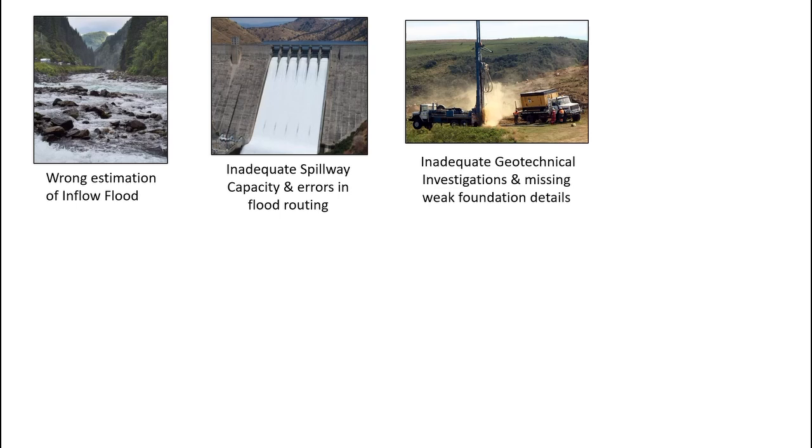Next reason is carrying out drilling and getting information about foundation or geology of the area. These geotechnical investigations give vital information. However, many project owners tend to do fewer investigations to save time or for other reasons. Inadequate investigations will not give the clear picture of foundation or geological details.